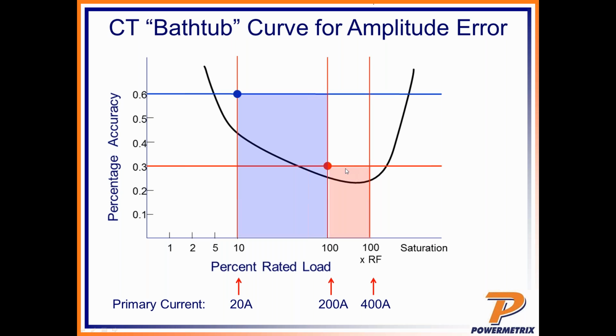So these are things that we talk about when we say, are we using the right CT for the installation? Are we using rating factors to our advantage? We want to be down in this area when we're making calculations, not up here, right? As we get even lighter load, right up in this area, it's really just starting to become noise as a signal, so our accuracy really goes off the charts when we get really, really lowly loaded, okay?